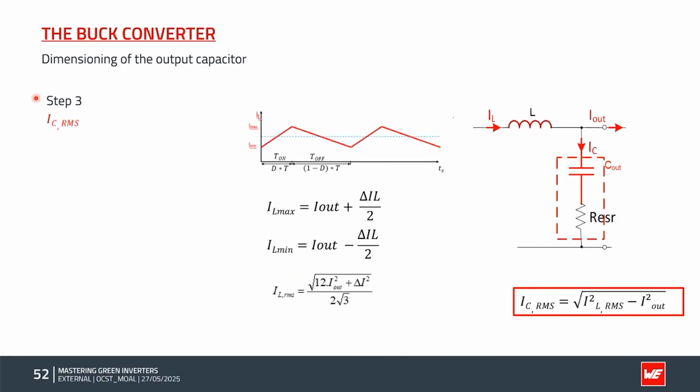Moving on. That's two parameters now. The final parameter for selecting a capacitor: we know the capacitance value, we know the ESR that is needed. Now we need to know the RMS ripple current that the capacitor can tolerate or can carry. That's based on the equation that you see circled in red here. Just to point out, these equations are associated with the buck converter. It will not be the same for the boost or for a SEPIC. So you will need to recreate some of these equations for these other topologies as well in order to calculate the relevant values as I've mentioned them.